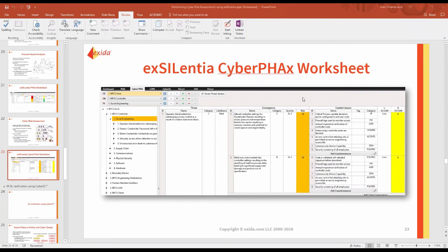Someone asked, why is the SIF not protecting against these risks? And that's a very good question. In some cases, I would say it's possible that a SIF could protect against the risk. It depends on how the attack basically happens. So if our initiating event in the safety case was basically that the BPCS failed, then you would have the safety instrumented system maybe act and mitigate that risk.